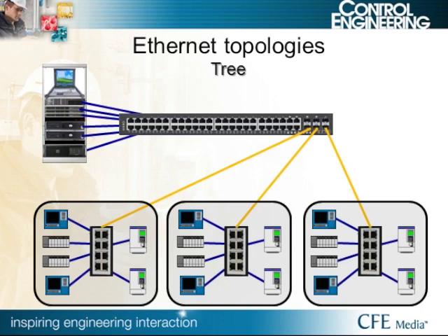In this example, we are using a commercial-grade 48-port switch that is located in a controlled environment where the servers reside. There are fiber optic cables extended to the panels from that switch that contain switches and the control equipment, PLCs, drives, and HMIs. Since fiber is immune to EMI and RFI, and you can have runs as long as 70 kilometers, though most fiber run within a building is using multimode cable, which has a distance of 2 kilometers.